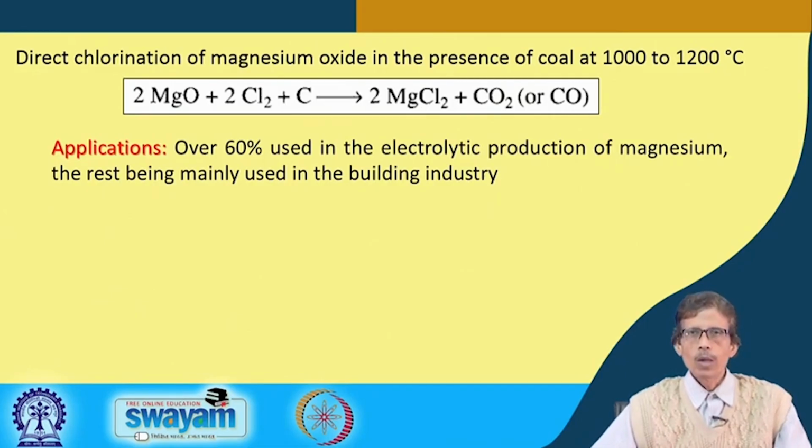That means at low air presence, we have to remove the oxygen. Whatever oxygen is present in your magnesium oxide, if it is removed at high temperature as oxygen gas, should be consumed by your carbon. That carbon will consume that oxygen to make carbon monoxide and carbon dioxide.